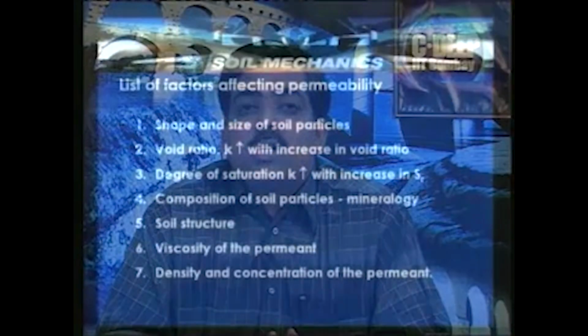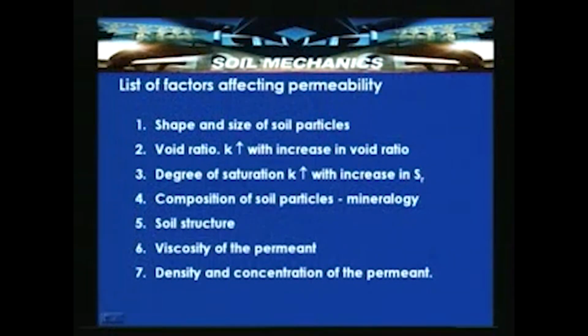Compactive effort, which is not listed here, can also influence the permeability. And viscosity of the permeant, or density and concentration of the permeant. So, these are the factors which can influence the coefficient of permeability.